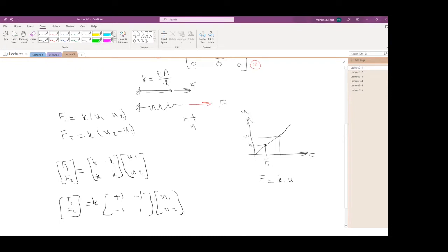So we brought the finite element from this origin, so that if you go back to the origin of the finite element method, it goes all the way back to this Hooke's law. And based on Hooke's law, we develop what is called later the stiffness method, the direct stiffness method, and then the direct stiffness method resulted into the finite element method. And in some way, we have extended the concept using the finite element method. We have extended the concept into any number of dimensions.